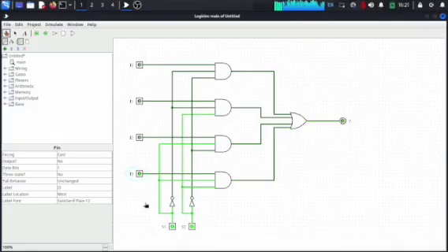You get it? So if it is 0, 0, this one outputs. If it is 0, 1, the output of the second. If it is 1, 0, the output of the third. If it is 1, 1, the output of the fourth. That's how a 4x1 multiplexer works, based on the selector's value S1, S2.